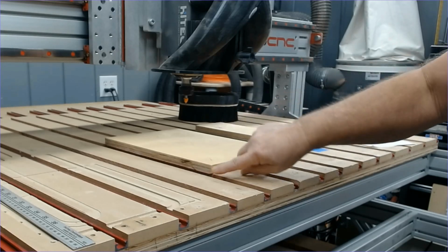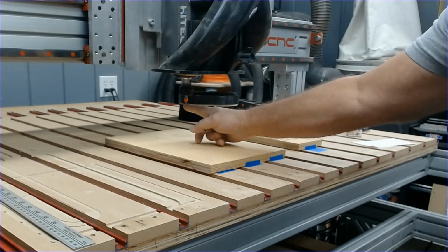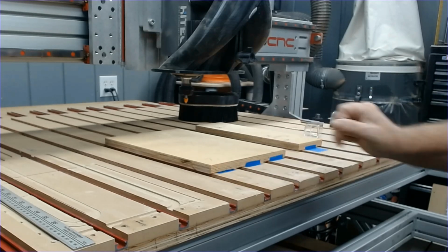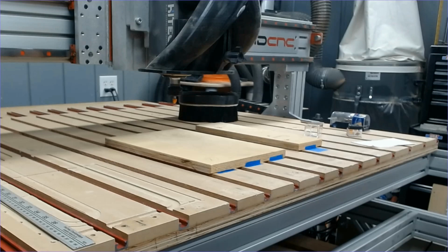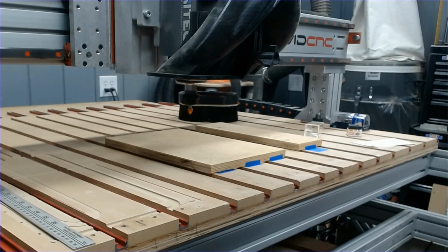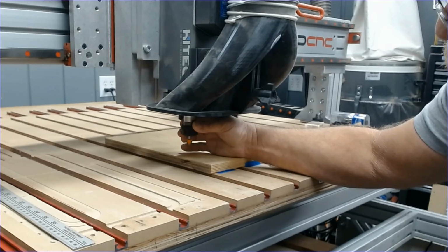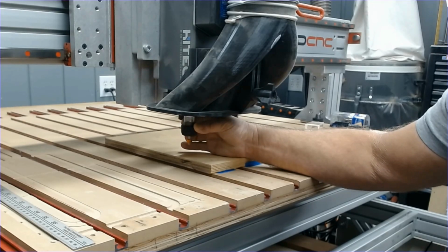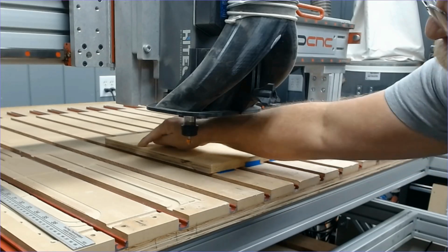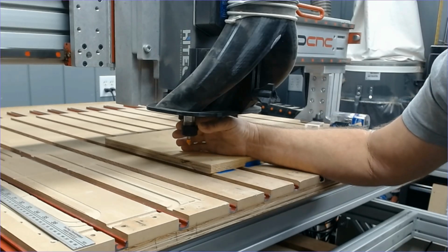If you're doing one of the corners of this piece of material, you want to bring the tip of this bit right to that corner. So let me go ahead and bring my gantry forward, my X over, and I'll bring my Z down. Now what I want to do is turn this bit so that I have the carbide flutes running in the Y direction, parallel with my Y axis. It doesn't have to be perfect, but it needs to be pretty close.